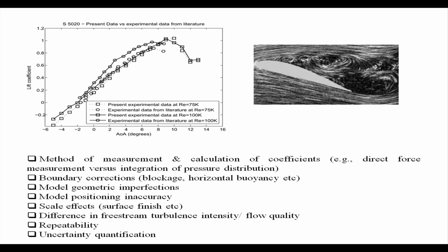It is the pressure and it is also the shear stress, the skin friction. Both of them are important. And if you are just integrating pressure and hoping to get your data, you are wrong, because you are neglecting the skin friction altogether. You are missing out somewhere. So, that might be one of the reasons why we are not able to match it here.